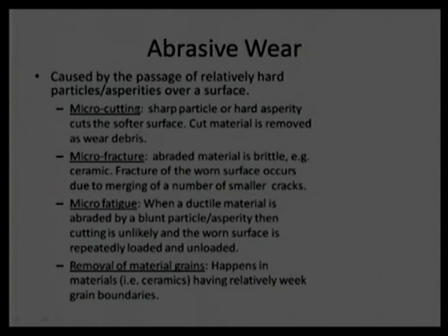And whenever particles or material get removed from the surface, we call this wear debris. If the material is getting displaced, maybe initially due to fatigue or some sort of plowing effect, we will not be able to gain wear debris, it will be just a deformation of the surface. Wear debris is a loose particle, and those loose particles may further increase or decrease the wear rate, depending on the operating parameters.